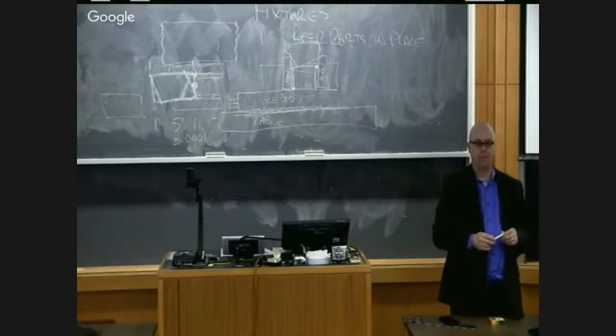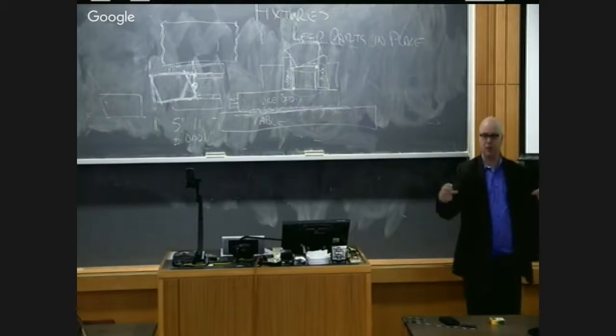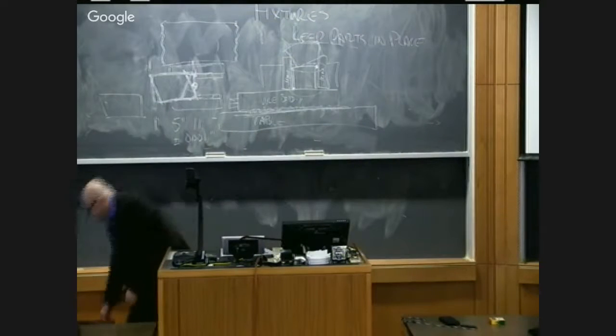It should be more than the frictional force. Right. So there's some maximum frictional force that's possible based on the normal force and the coefficient of friction, right? And so if our cutting force exceeds the maximum possible friction force, the part flies out of the vice. Somebody's been here when the part flew out of the vice. It's loud, right? Okay.